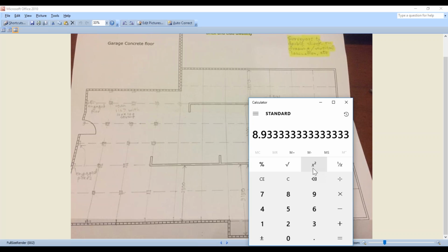So to work out my spacing, I divide the length of the wall, 13,400, by my 9 spacings. And therefore my spacing, the way I worked it out, would have been 1488.88. So my stumps wouldn't have looked as symmetrical and nice as Subert's, because they would have just been every 1488, and that's how I would have worked them out. Once we did that, I'll bring up my Australian standard again, so bear with me a second.